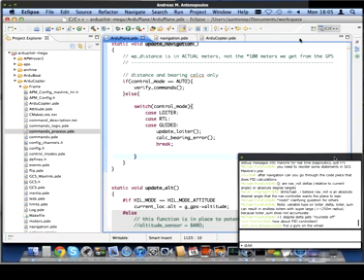Now, in order to do auto launch, you really do need a compass rather than a GPS. The reason for that is that the heading for a GPS is notoriously unreliable at very low velocities. When you're initially taking off, you will have an extremely low speed, which means your GPS heading is likely to be complete rubbish. It might be pointing in the exact opposite direction the plane is pointing.